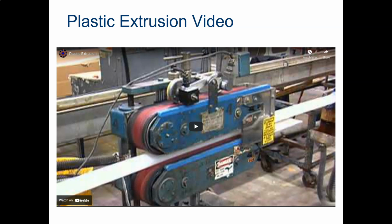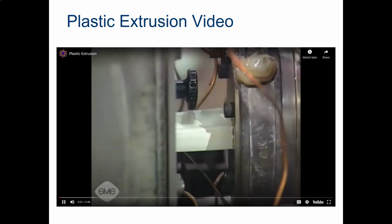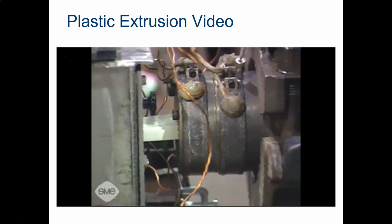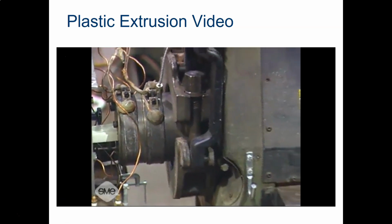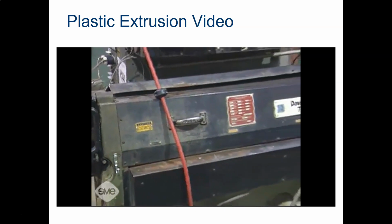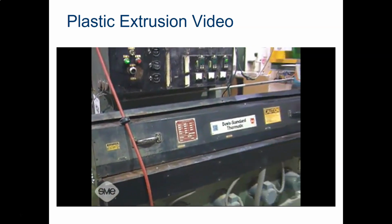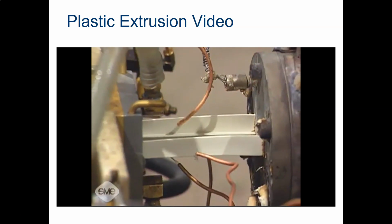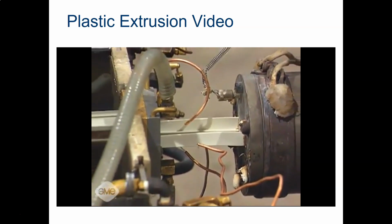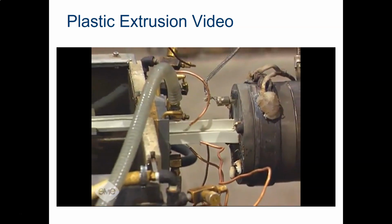And if we're going to consider metal extrusion, let's consider plastic extrusion as well. Plastics extrusion is a continuous process in which thermoplastic feedstock material in an extruder is transformed into a molten, viscous fluid using heat and mechanical shearing. This thermoplastic fluid is then forced through a die opening where it is shaped and cooled into solid form.